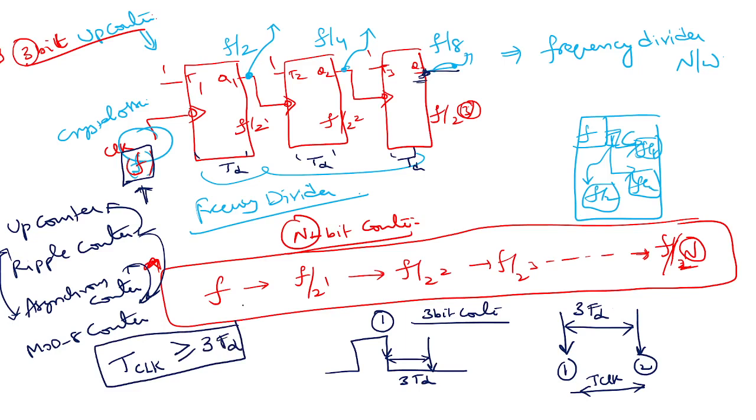Anything greater is fine, but it cannot be less than 3 times TD, because you are not allowing the flip-flop time to generate a stable output. Are you getting it? Since T clock must be greater than or equal to 3 times TD, 1 over T clock, if I divide...